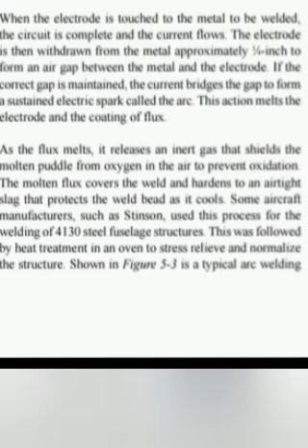This action melts the electrode and the coating of flux. As the flux melts, it releases an inert gas that shields the molten puddle from oxygen in the air to prevent oxidation. The molten flux covers the weld and hardens to an airtight slag that protects the weld bead as it cools.